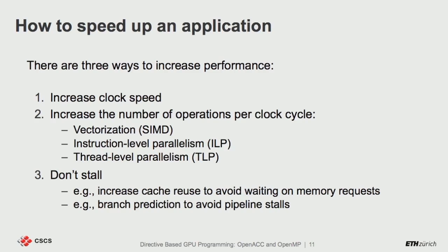And the third is to design the processor such that we don't have to stall, or I mean the application that we write. What is a stall? A stall is when the processor cannot proceed. So it cannot fetch another instruction to run because it's waiting for memory accesses, or there are dependencies between instructions, or there is a branch prediction. So what does branch prediction mean?